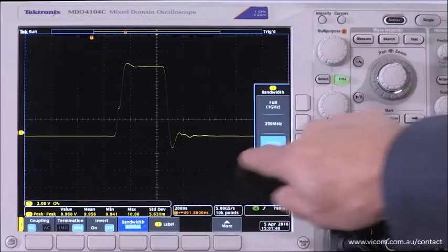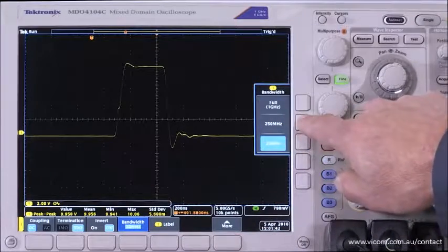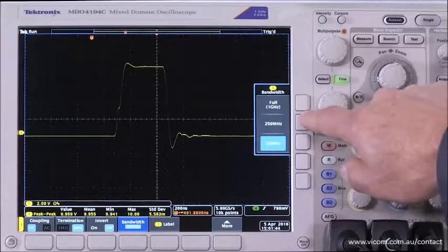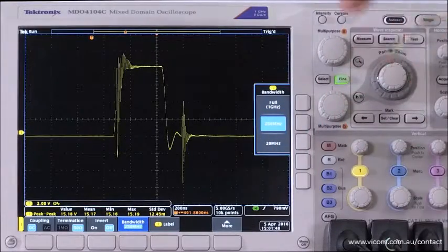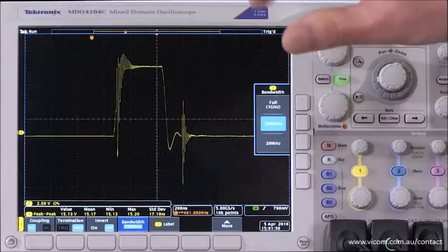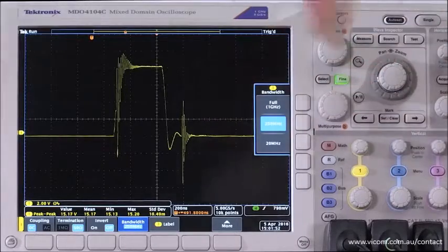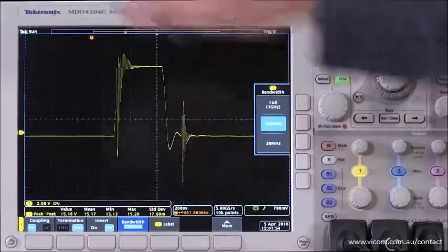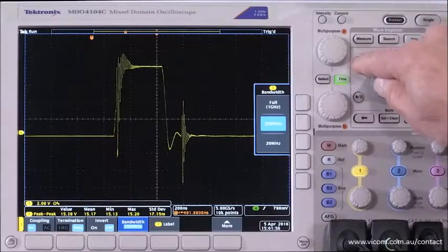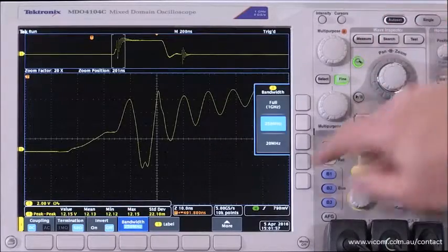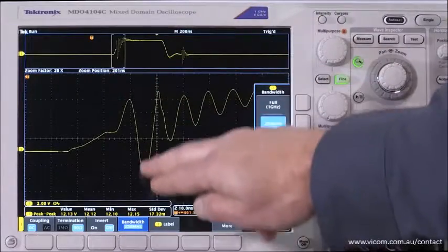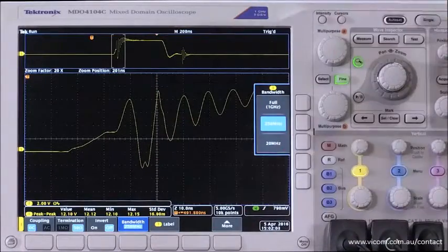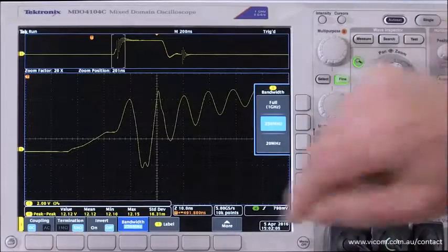What if I open this up to 250 megahertz? So I use a 250 megahertz measurement system, and all of a sudden I see this detail. This is the high frequency information that is masked when I use a low pass filter, which is my measurement device on this measurement. Let's zoom in and see those details. Here we see about a 100 megahertz ring. And we see a hint of something else, but we don't have enough bandwidth yet to see the true measurement.